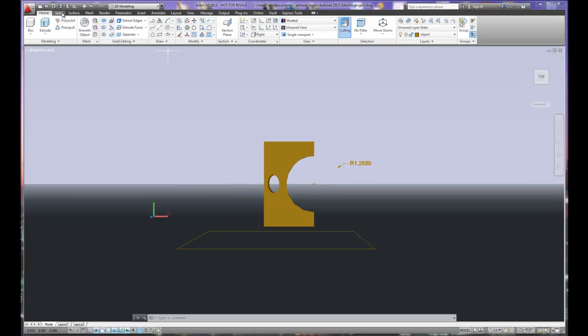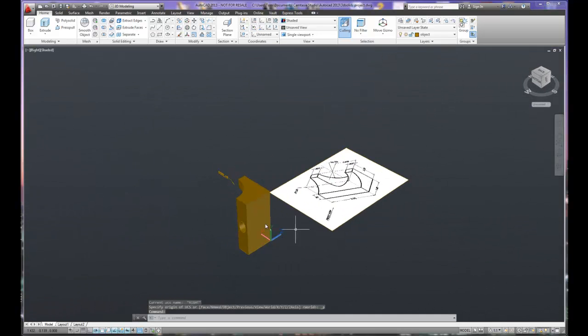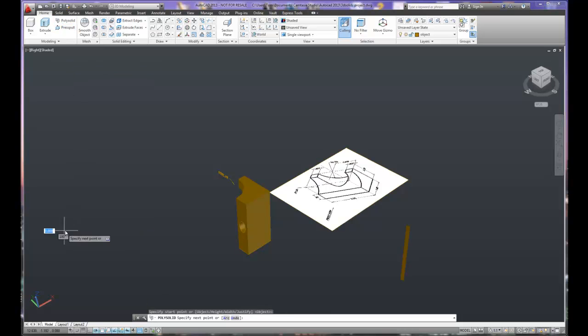Because the poly solid allows me to draw on the surface, and it's going to draw on X and Y. And it's going to create roughly like an 8-foot high wall. And so let me go to the UCS previous. Let me jump back and go to the view. This will work a little bit better. Let's hit the UCS previous again. There we go. X and Y are now on the base floor. We're going to do the poly solid on the floor here.